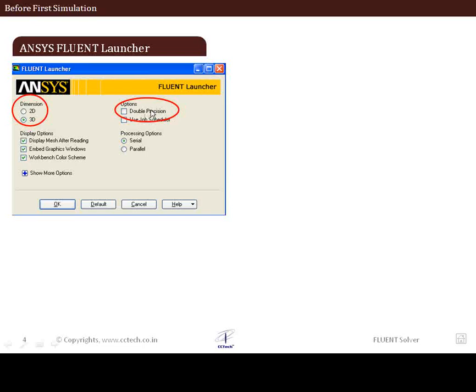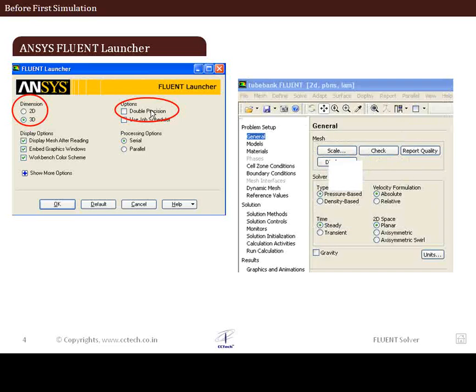Now what precision means is that you're trying to include more locations after the decimal point in all calculations. What it further reflects itself into is that you include more accuracy. But there are problems in which it will not really help to increase the accuracy. It's not really going to serve the purpose. And choosing a double precision solver surely means a bit higher computational effort is required. But this is sometimes necessary in certain classes of problems. We're going to look at it in the next slide.